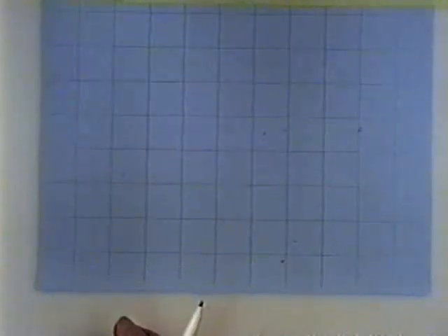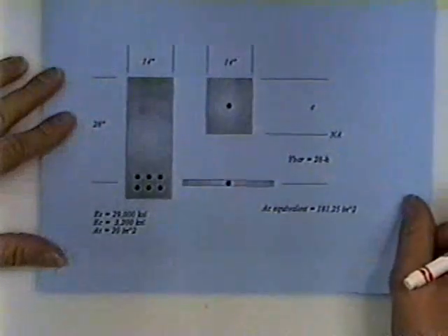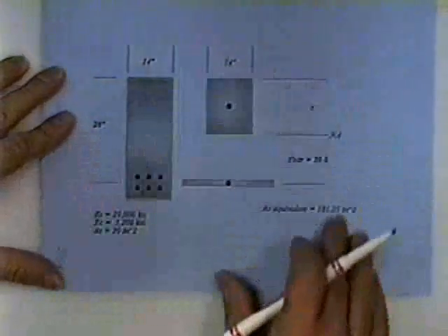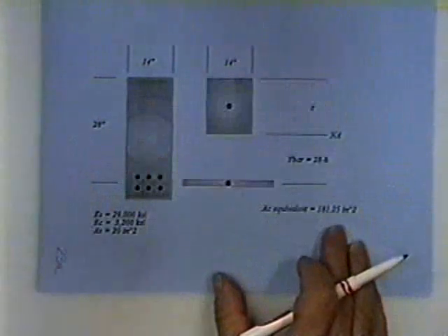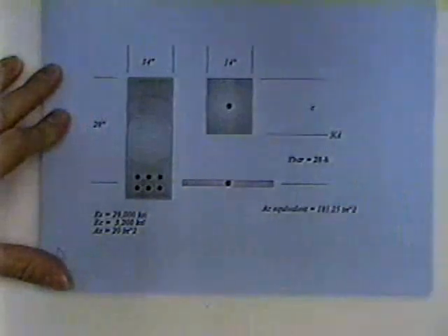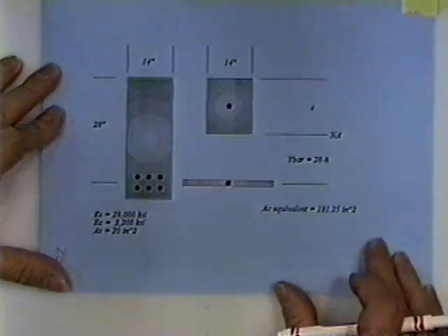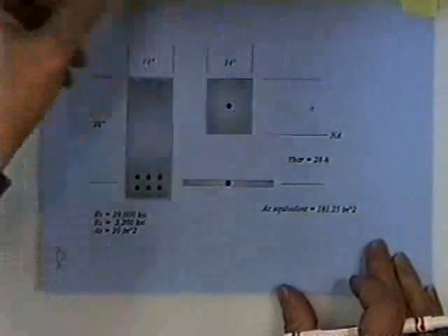All right, I'm going to skip page 22 and go to 23. 22 is really just like the rest of them. It's just another example of I0, which you look up in a book or in a table, and the AD squared terms, which you calculate. Because what I want to do is show you how to get the moment of inertia or how to get the centroid of a concrete or a mixed beam.